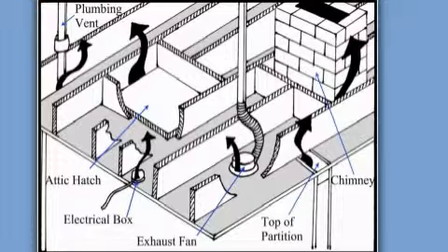So here it shows the typical places in an attic plane where we find leaks. Electrical boxes, plumbing penetrations, the attic access hatch, around a masonry chimney, around an exhaust fan, and the big diffuse leak is where the drywall doesn't seal airtight to the double top plates on the interior partition walls. So we're always sealing our ceiling drywall to the top plate 2x4.